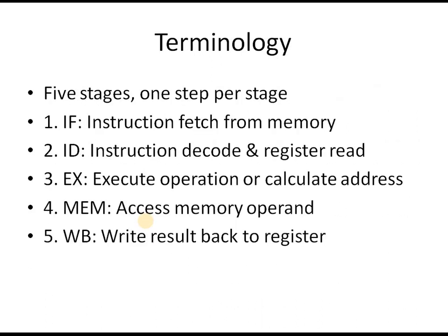Some terminologies we will use in today's lecture: 5 stages, 1 step per stage. IF, instruction fetch from memory. ID, instruction decode and register read. EX, execute operations or calculate address. MEM, access memory operand. WB, write result back to register.